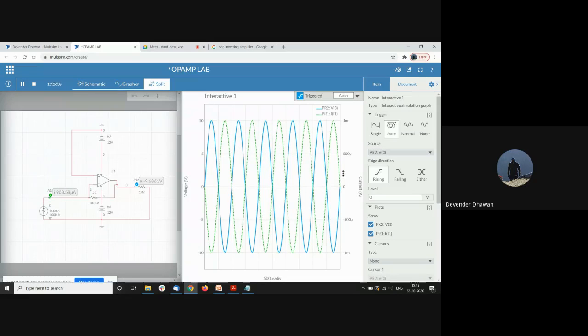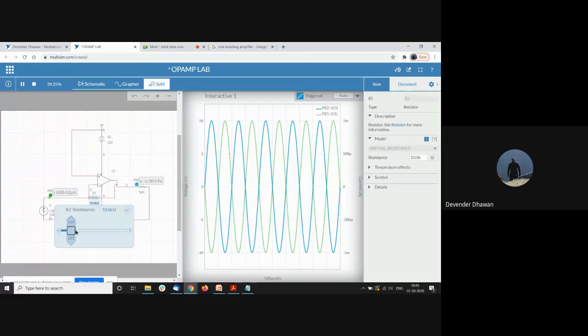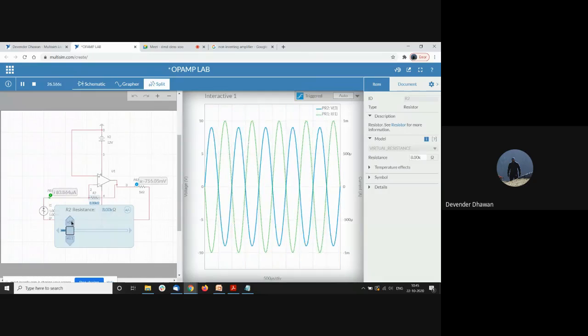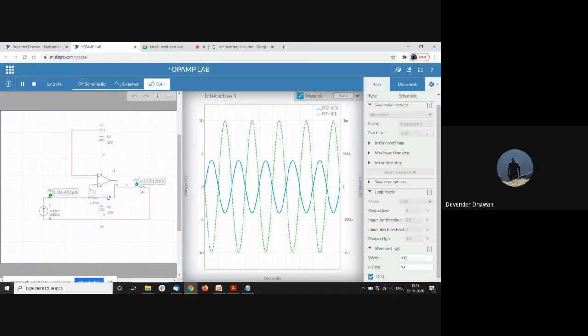This side here is the current axis, and this is the voltage axis. You can see the current is 1 milliamp here. If we try to increase the voltage, we are actually surpassing our cutoff, so that is why it is converting to a square wave here. If we decrease it, 4 into this, we are getting 4 volts. So this is how this simple current to voltage converter works. This is again a very simple circuit. Any further question on this?